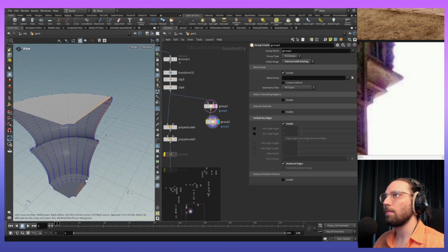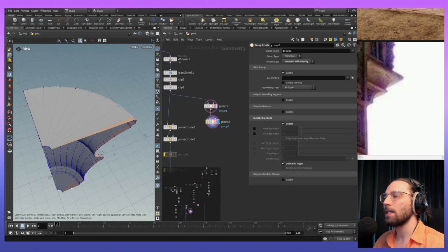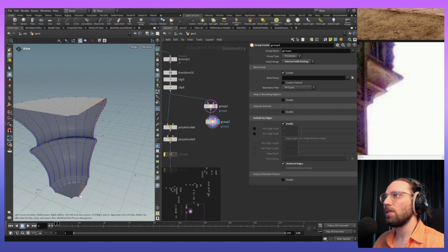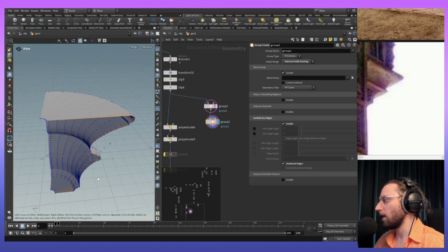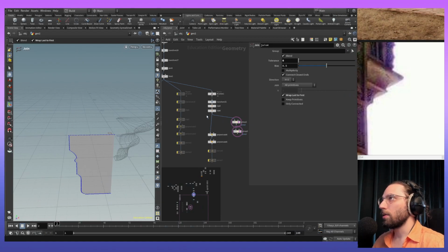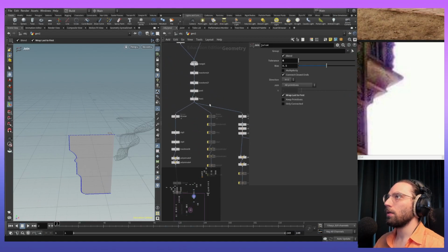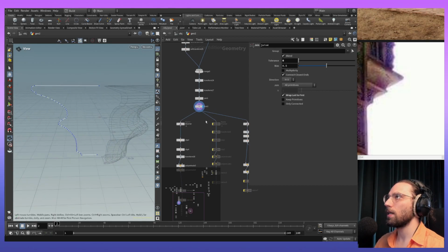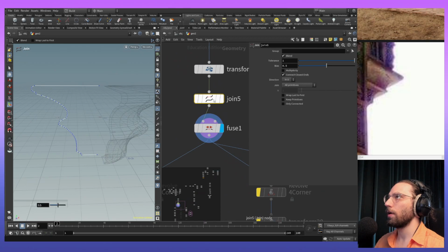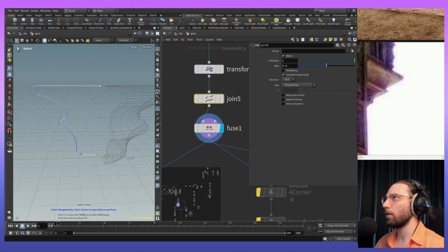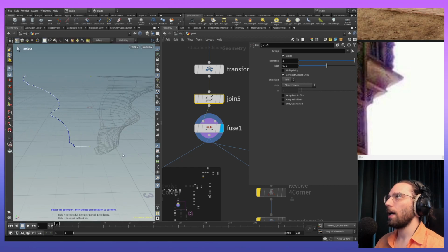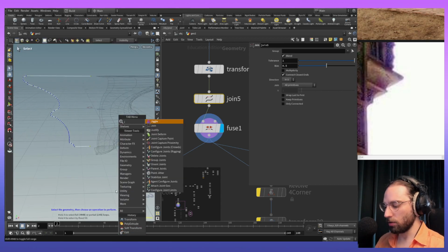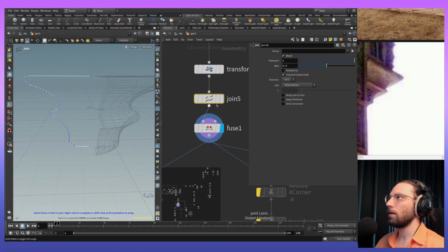Might be something, we might be missing one more thing. And that is, I think, because these edges are not closed. That could be our problem here. I'll check it and let you know. So we will start troubleshooting, guys. We will go right here, and we will join just like we did yesterday, and it's a step that I've forgotten to take. I will go back to this join, and I will type 2 now, select these two, and type join again. So we'll have 2 join nodes.